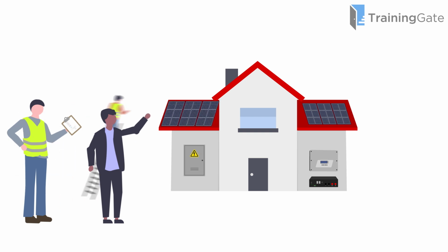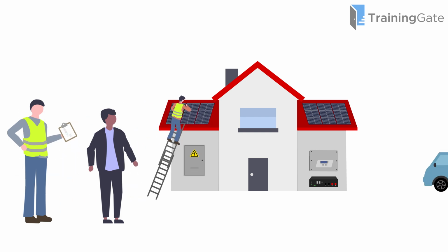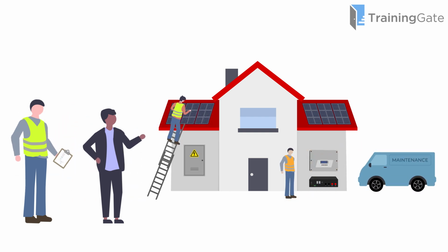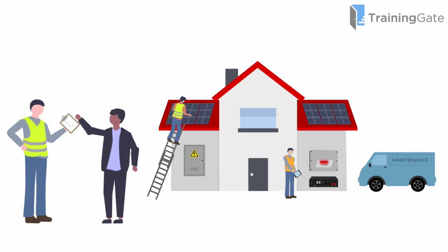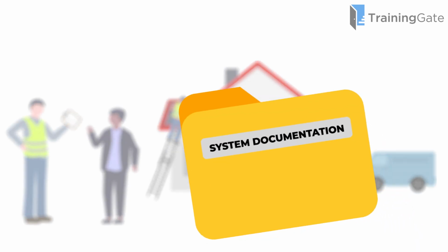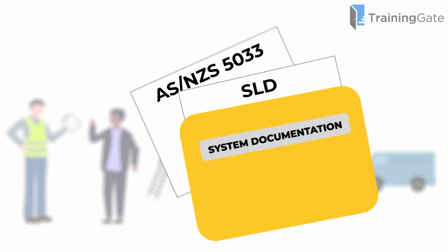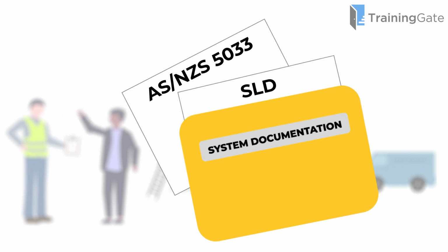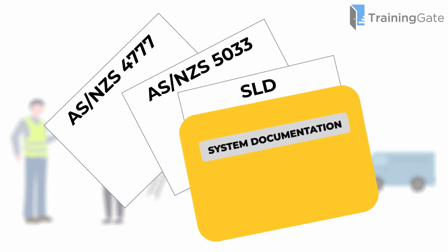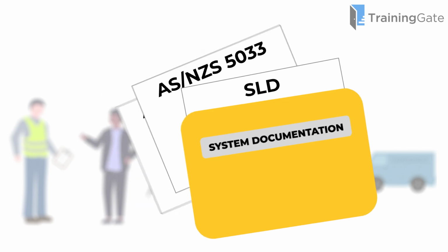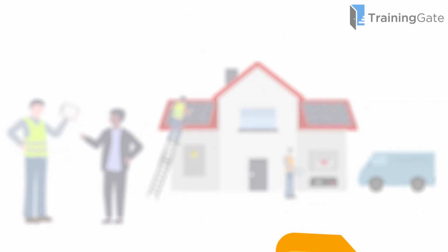SLDs are commonly used during equipment installation, maintenance, system commissioning, and fault finding. They support electrical safety, reduce downtime, and improve system reliability. In many cases, SLDs are part of the documentation required for compliance with standards such as AS/NZS 5033 or 4777, or for grid connection applications with the DNSP.